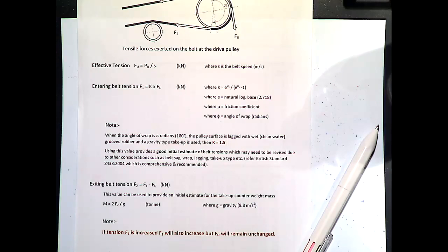Misalignment, bad misalignment. But for it to go for that long and to get that bad, people don't look at these things sometimes. Look at this belt here. This is a take-up. There's a whole lot of material dropped inside of the belt, and so material here is just going round and round. There's lumps. They're just about ready to pop through the belt.